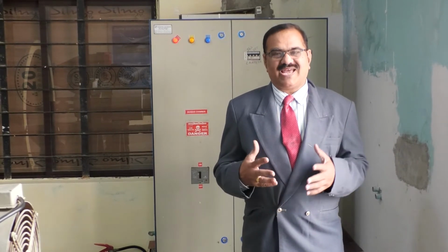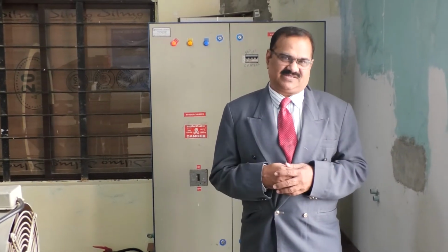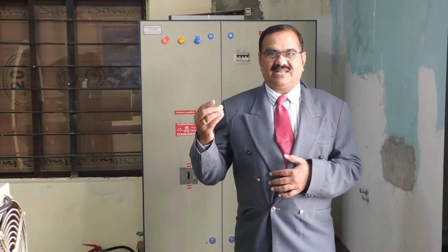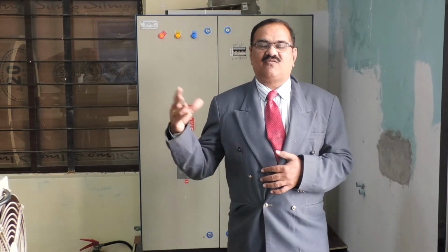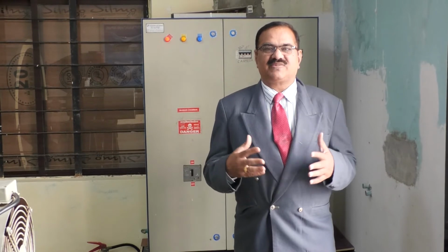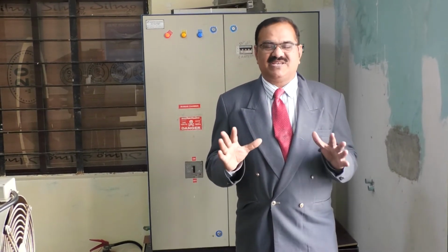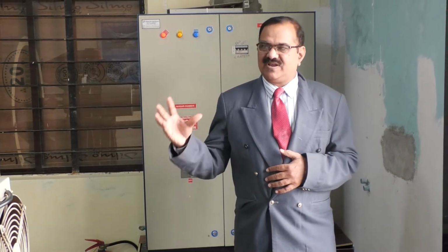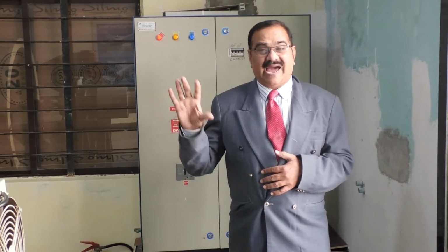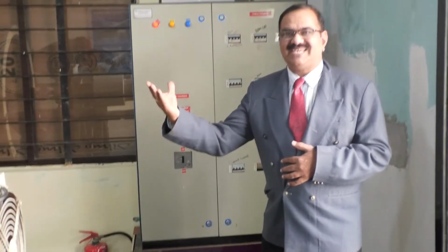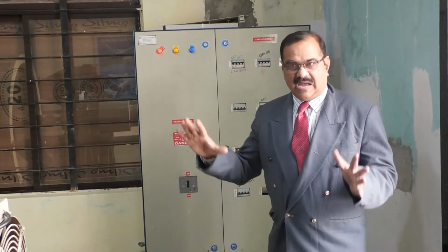How to do the calibration, and why to do the calibration. Every time we have to assess that the given values of the wind tunnel are matching the required values. So every time we have to undertake the calibration of any measuring equipment. Here we will be calibrating the speed of our wind tunnel, and as per the RPM of this motor, how much velocity it is producing. So I will start here.